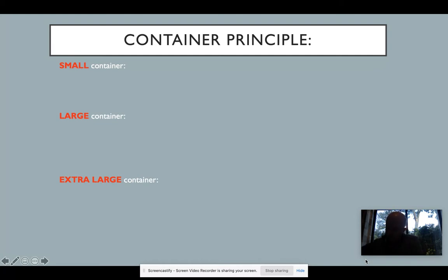And if you read the article, or the question, if you like, it explains this idea of the cubic law, and the doubling of height, width, and size of a tanker leads to being able to build proportionately a much bigger container for significantly less cost when you look at the overall amount of material required. So if we take as the example, you can see that we've got a 2 meter by 2 meter by 2 meter container. So the volume is 8 cubic meters. But if we double the size of that to 4 meters by 4 meters by 4 meters, our volume is significantly increased to 64 cubic meters.